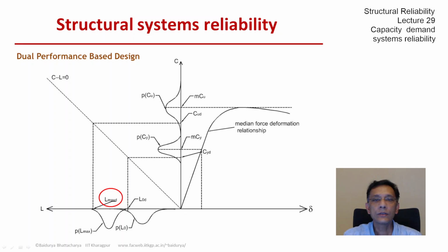So this gives an idea that for the same structure, we can be interested in two or more performance levels and set different requirements, which would also be governed by different regimes of structural mechanics. Maybe for yield or below yield, we'll be happy with linear, elastic analysis, and for near ultimate, we would probably need to consider beyond-yield behavior, plasticity, nonlinearities, and so on.